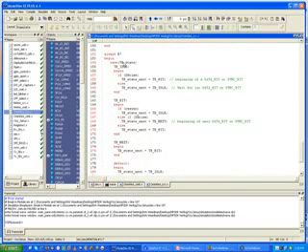So then in the next always block down here, everything in this block is derived off of that TB state, the output of those flip-flops. Here I've said that if I'm in the idle state, then I wait for this condition, and then I say that my TB state next is equal to this state. So when the next clock comes, let's say I'm in the idle state, and let's say that this occurs, then this becomes TB bit. So then on the next rising edge of clock, this state value gets clocked into those flip-flops. And that's how we change state.